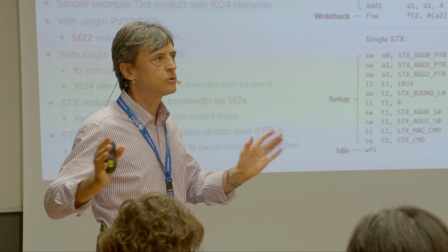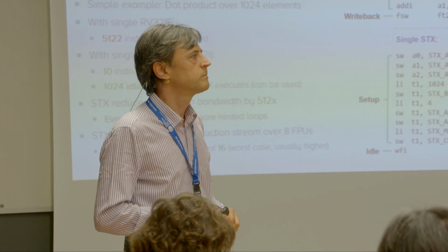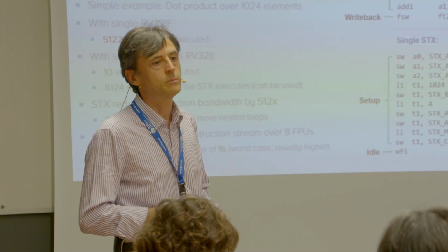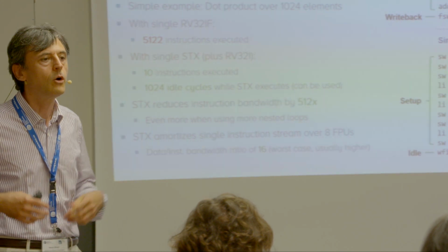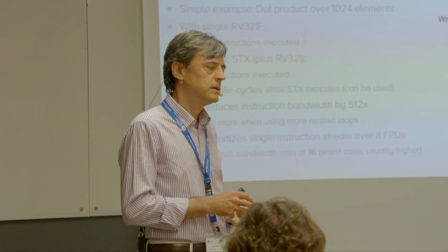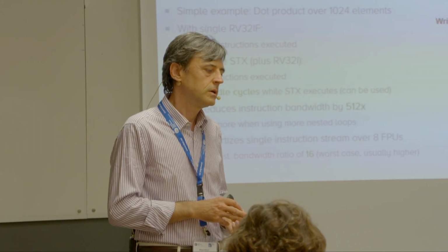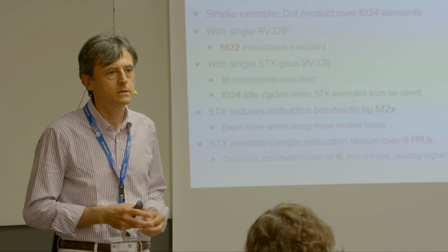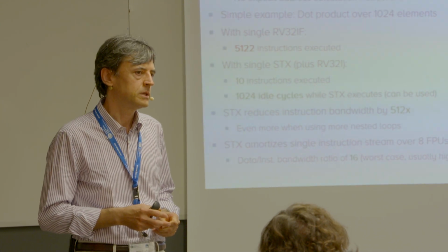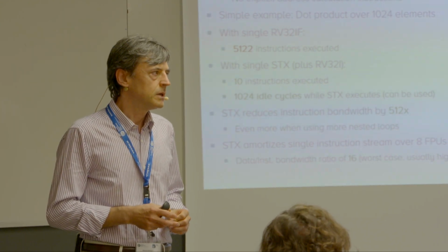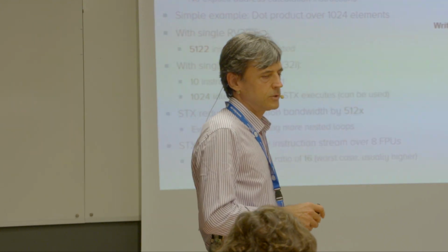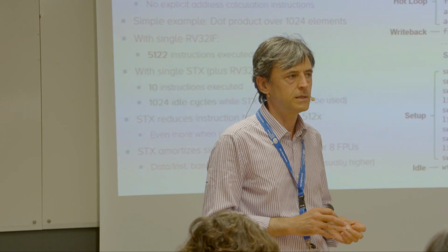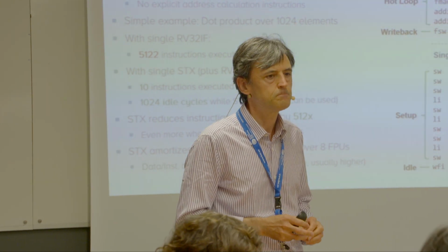And the longest vectors you have, our machine, I can tell you, targets a minimum of 256 elements, double precision floating point, which is considered a long vector size in the present technology scenario. The longer the vector, depending on the applications, of course, the more locality you can exploit. I am not a software guy, so I cannot tell you the application that can actually fit this scheme, but that is the microarchitecture solution that we are looking at.